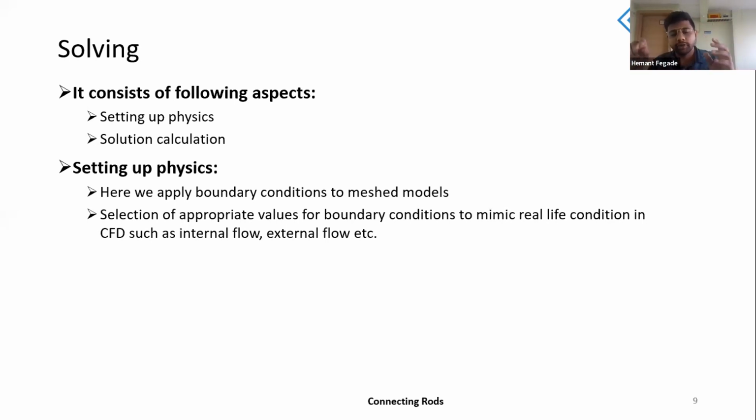Essentially the overall surface of the heat sink is going to be a wall, because it's going to generate some sort of heat. If it's generating heat, we need to give it a heat source. So that is a boundary condition. When you're talking about walls, inlet and outlet, at the inlet you need to give velocity, because your air is going to move at that velocity from the inlet.